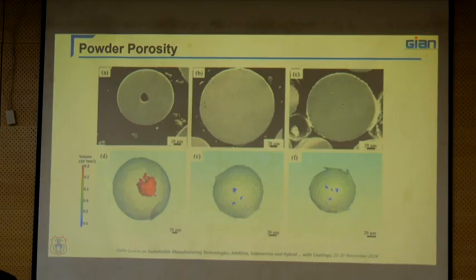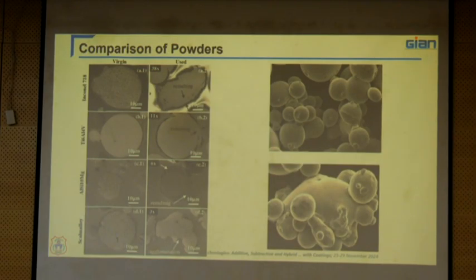Because these challenges will take place when we are buying very high-quality powders, we need to understand these things. If you see, some researchers have worked on this: the pure original powder particles and the reused powder particles, and how the microstructure looks with Inconel, titanium, aluminum or Scalmalloy, and this is what the reused powders look like.